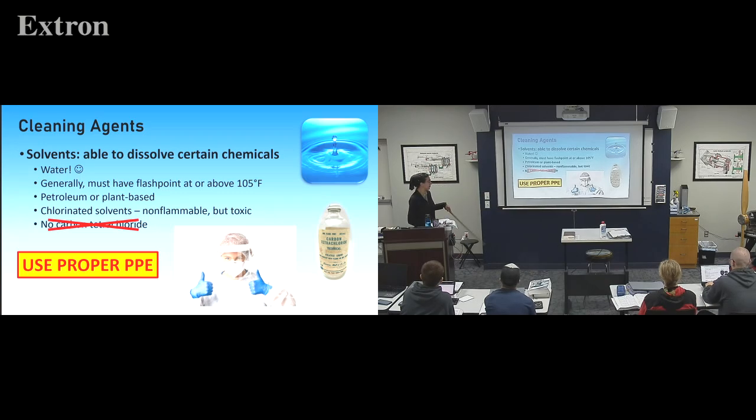And always use proper PPE, personal protective equipment. Know what chemical you're working with, know how hazardous it is, how much eye protection, whether you need a full face shield, what type of gloves. Are you aware of the nice chart out by the gloves? Lyle put up a chart showing what gloves should be worn for what chemical. It's on the white cabinet right where the gloves are. Very, very useful.